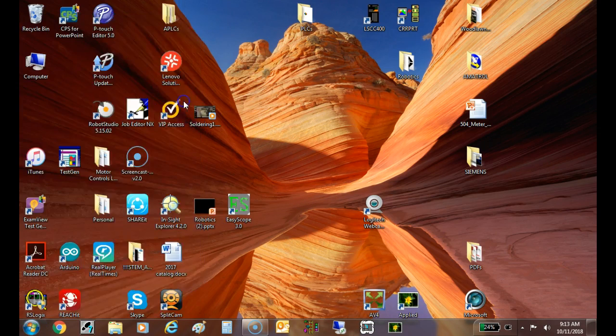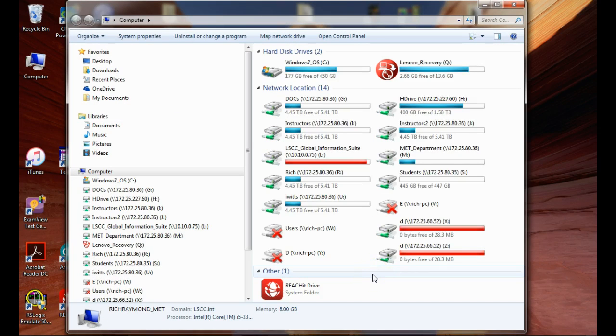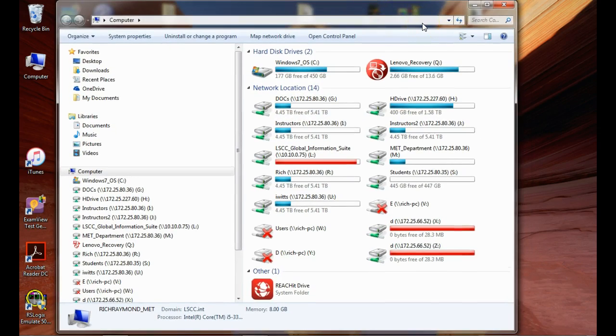So just go right down the line. We have the transformer. What comes next in our block diagram? Rectifier. Okay, so we'd have to choose diodes. We'd have to say, okay, we need a rectifier that can block, right? We consider two things for diodes: how much current they can handle when they're forward biased, and how much voltage they can block when they're reverse biased. That makes sense.